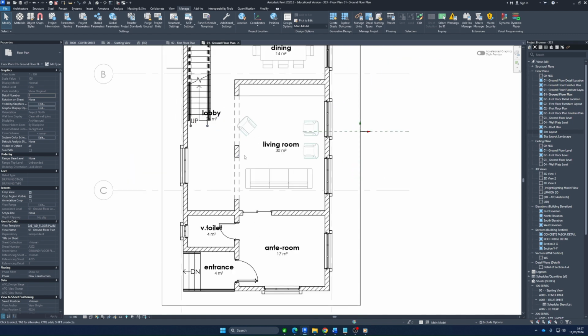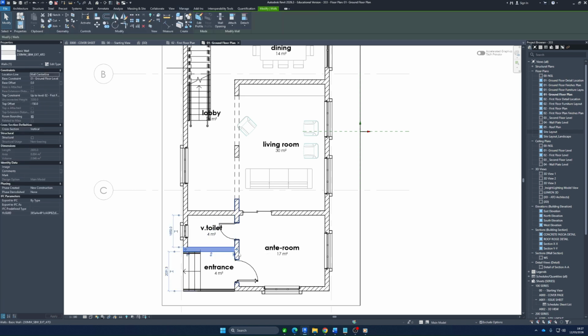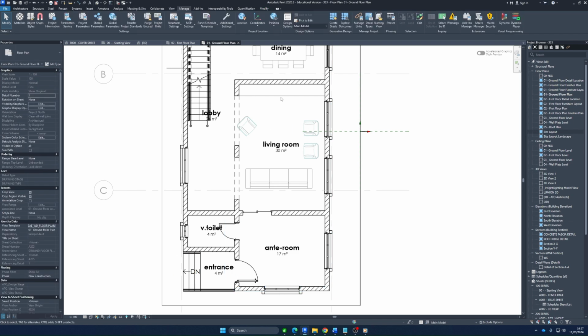Now that we have done this, in the main model, which is this, and also visible here, we can't select any of the elements we've added. Only the elements that are still left in the main model, that's what we can select. But all the ones we've added, we see that they're not selectable because we've moved them to our option sets. So what we can do is to now go to our option sets. If we click the drop down, we'll see the different option sets and the options inside option sets. So this is the option set we're working with, and we'll go to option 1.